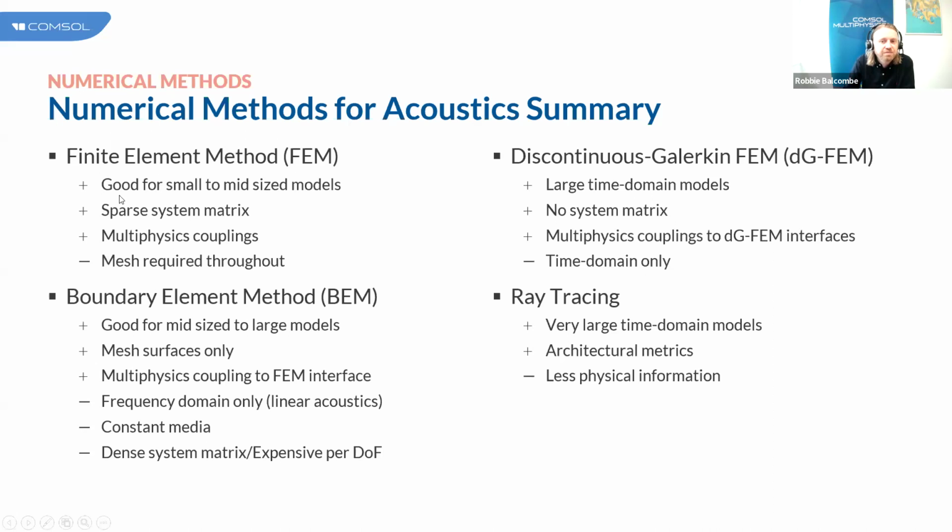We also have a large number of multiphysics couplings for the finite element method within the COMSOL software functionality. The drawback, however, is that we require a mesh throughout our modeling domain, and this mesh will scale quite badly with respect to frequency in terms of the number of elements that are needed. We have a DGFEM method, which doesn't rely on a system matrix, so it reduces the cost of the solution process.